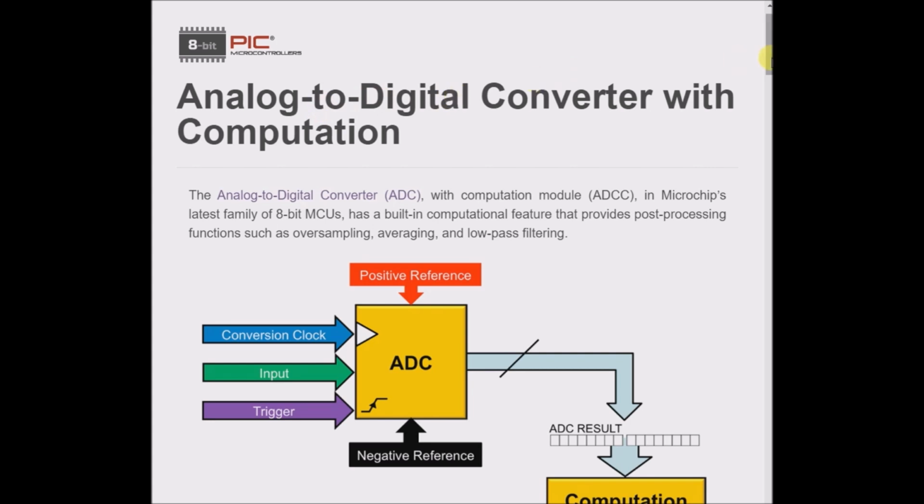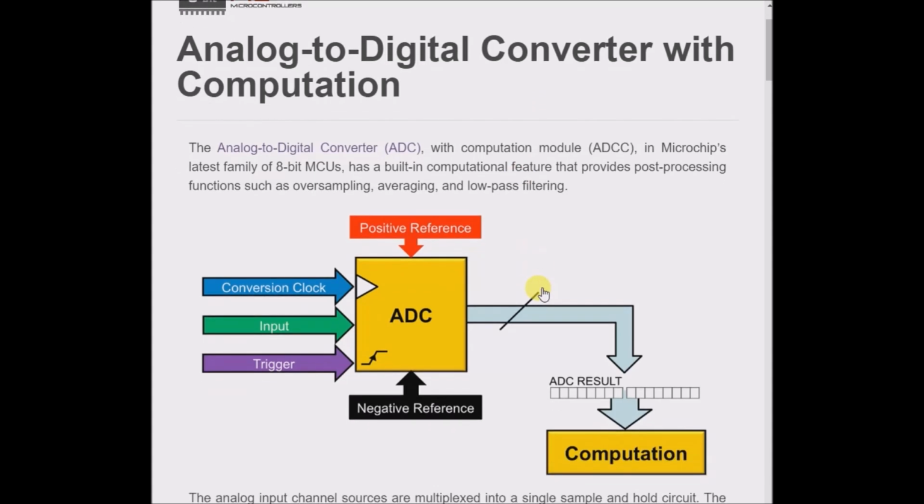Analog to digital converter with computation. The analog to digital converter (ADC) with computation module (ADCC) in Microchip's latest family of 8-bit MCUs has a built-in computational feature that provides post-processing functions such as oversampling, averaging, and low-pass filtering.